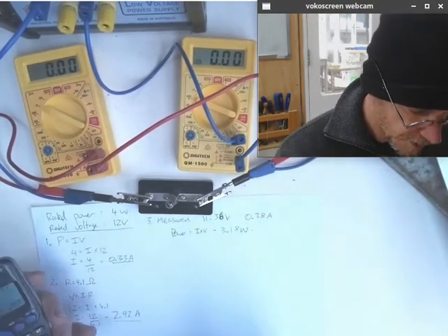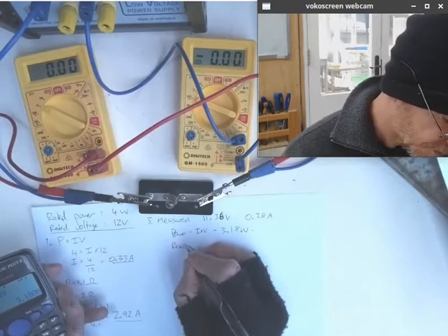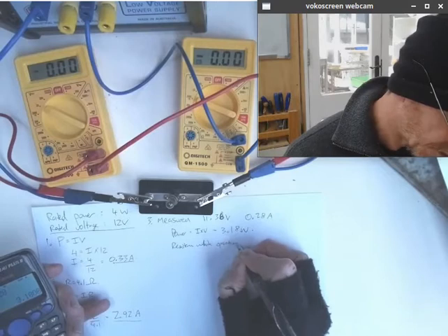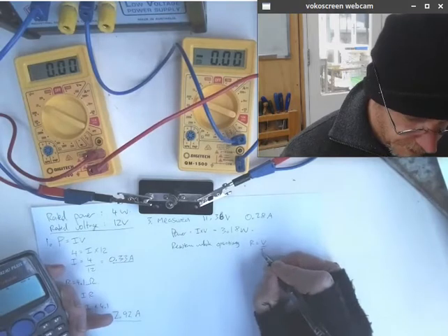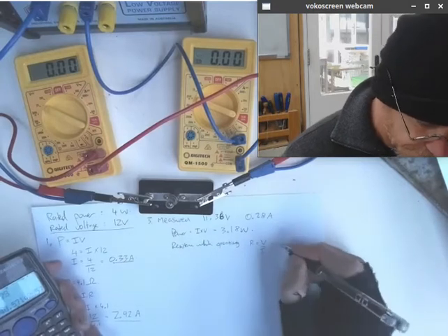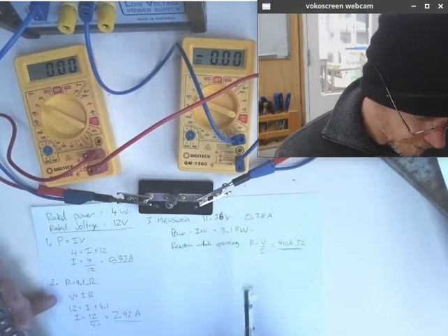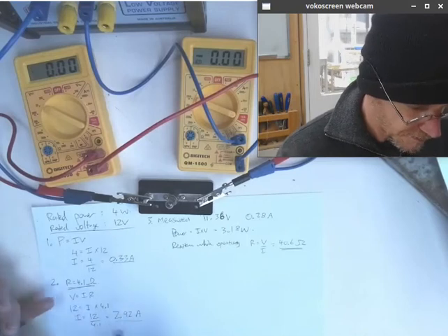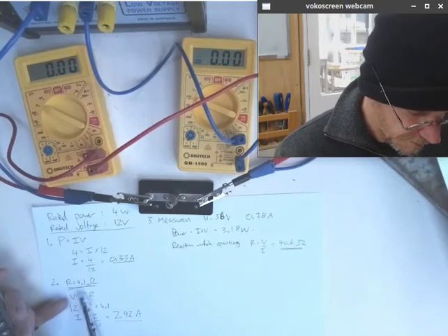And we can also work out its resistance while it's actually running. So the resistance while operating, and we can use Ohm's law for that. V equals IR, R equals V over I equals 40.6 ohms. So its actual resistance while running was 40.6 ohms, whereas when we measured it using the meter on the light bulb, it was 4.1.